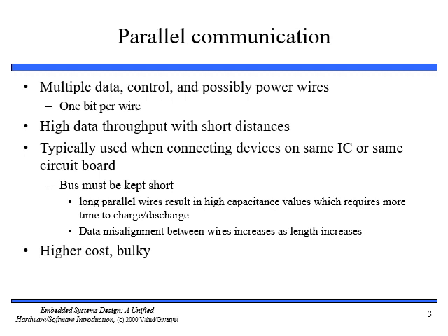In general, parallel communication is used when connecting devices that reside on the same IC or devices that reside on the same circuit board. Since the length of such buses is short, the capacitance load, data misalignment, and cost problems, as I told you earlier, do not play an important role. So let's move on to the next slide.